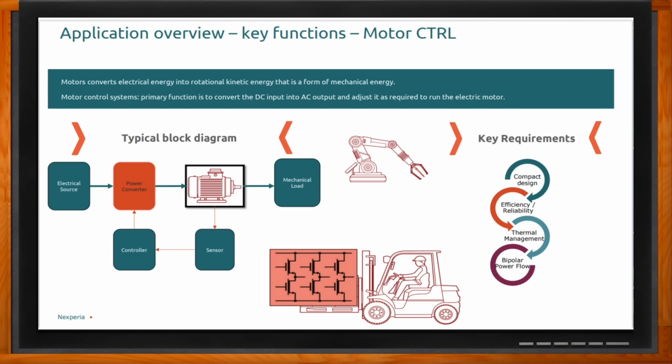Even in the same motor size, where you use, let's say, 1 pound of aluminum heatsink, with our approach with GaN and the higher frequency switching, you can reduce that by 50% easily and use half a pound worth of metal instead of 1 pound. And so aluminum is still expensive, and that gives you a pretty good idea where the savings will come in